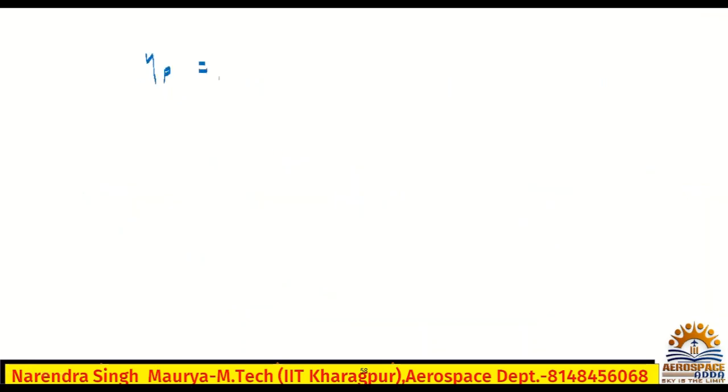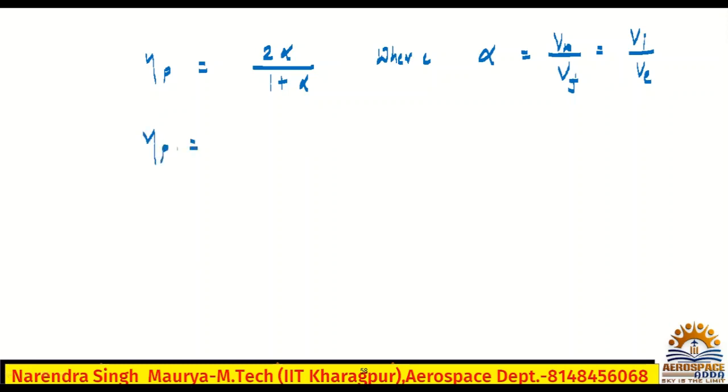I will give one short formula: 2 alpha divided by 1 plus alpha, where alpha is V infinity by Vj, or V infinity by V exit. J for jet velocity, E for exit, same thing. This is the propulsive efficiency, eta P.